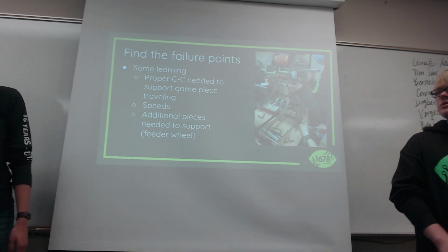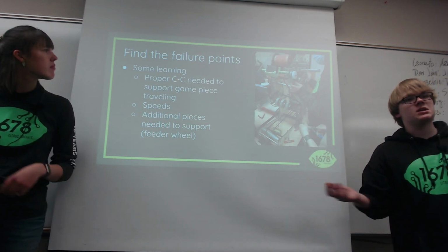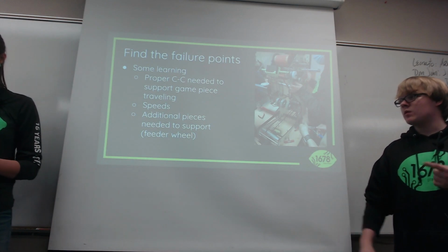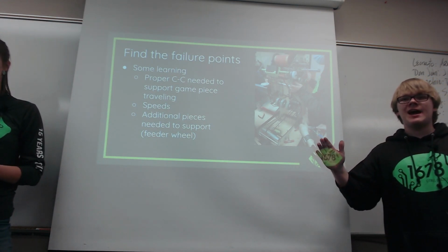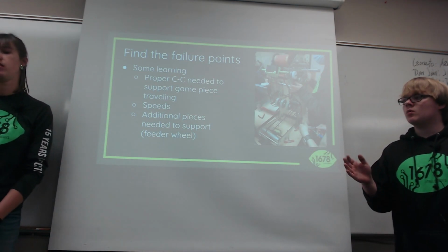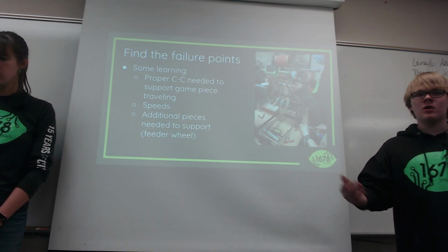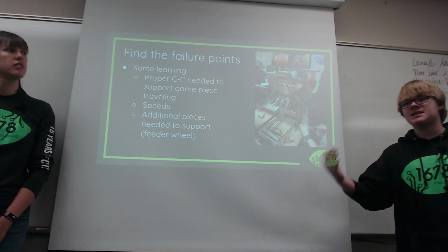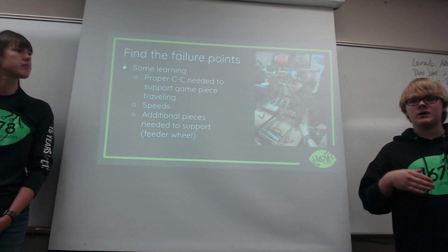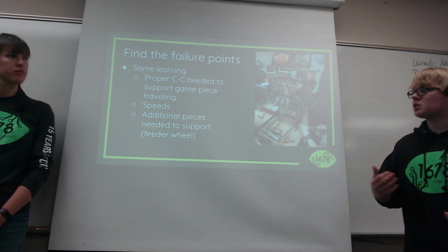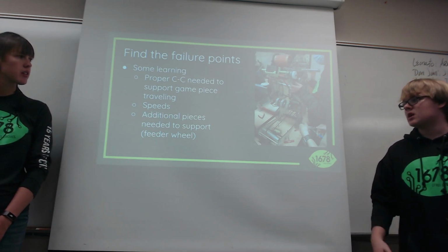Yeah, and then also these are just kind of the general things you want to be taking into your actual design. So the real goal of prototyping that we like to have is we want to figure out the center to center, so basically how much compression we want to be putting on these balls. We're trying to find the speed of how these balls like to move. So if it's an intake, we know that it wants to spin fast, but the question is how fast? Because that's going to influence your motor ratios, it's going to influence your motor usage for software. And you basically want to be figuring all of that out as early as possible, so when you're making these quick prototypes, you know what you're working with.